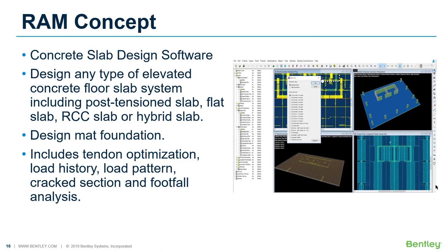Now comes RAM Concept. This is our best solution for slab design. Any type of slab system, whether that is a reinforced concrete slab, a post-tensioned slab, or a hybrid slab, some part of which is RCC and some part of which is post-tensioned, can be designed using this particular software. So it is very good with any complex type of slab system, and finite element analysis is performed in this software. And not only that, it has some great features like tendon optimization, load history calculation, cracked section consideration, and also footfall analysis.